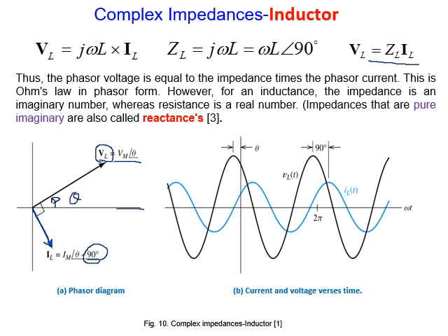Voltage leads the current, or let me say current lags the voltage. It's clear in this waveform in the time domain, as you can see here, the black is the voltage and the current is the blue. You see, we reach the voltage before the current. So 90 degrees is the phase shift between voltage and current in a pure inductance, a pure imaginary inductance.